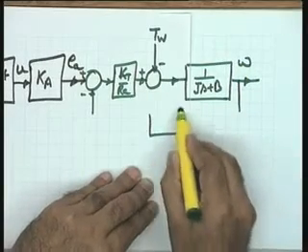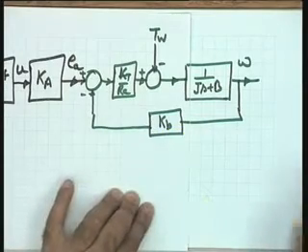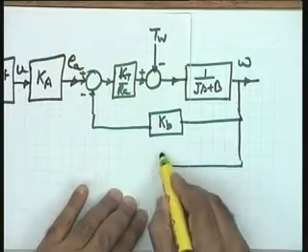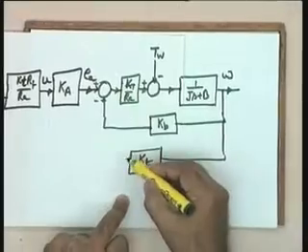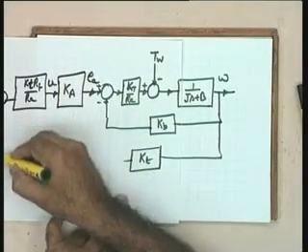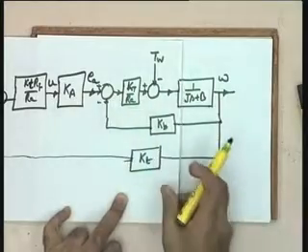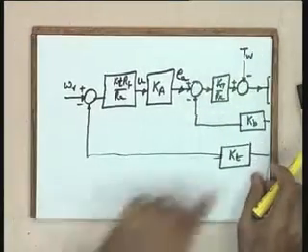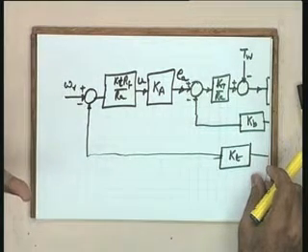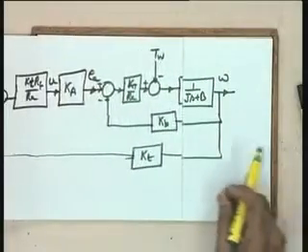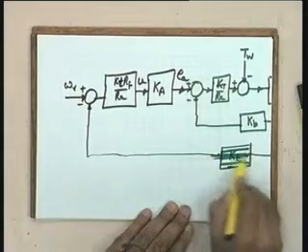From omega I take a loop to generate the back EMF signal. From omega I take another loop, it is a multi loop configuration now, through the sensor Kt, so that it is going to this particular summing junction and is giving you the primary feedback loop. I will put the diagram this way, Kt is going to the summing junction and is giving you the primary feedback loop. Oh, I am sorry, Kt has been taken over there, it is a unity feedback system, you are very right.